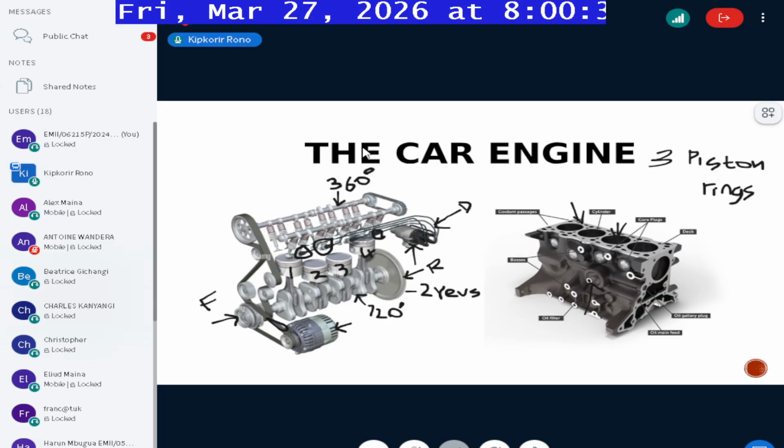So if you are operating in a very dusty environment, especially if you're going off-road, change your air filter as often as you can, because they are not expensive. I think an air filter is about 1,200 for most cars, between 1,200 and 2,000. It's not something that is very expensive, so it does not have to be changed together with the oil filter or the oil. They have no relationship. One functions as a lubricant as well as a coolant for the engine. The other functions as a filter for the air going into the intake manifold.